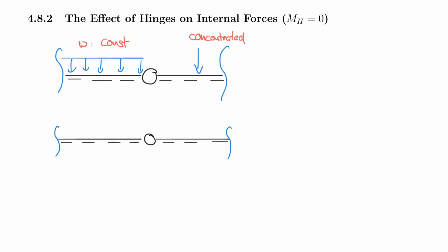And then whatever else happens on the system we don't care about right now. However, we also have still the same rules that apply, and that is that if you have a constant load case, your shear force diagram must be linear and your moment diagram must be parabolic. So I have no idea in this system what's happened to the left and to the right of it, but let's just pretend for a second it is parabolic here.